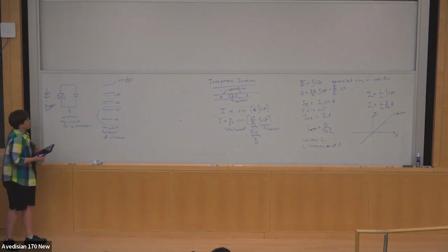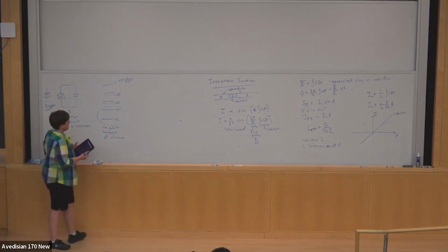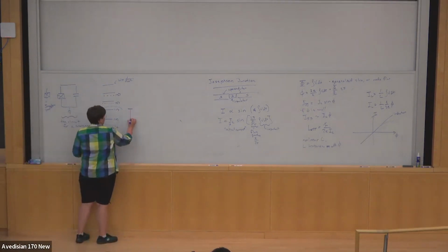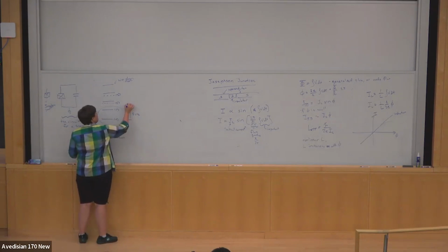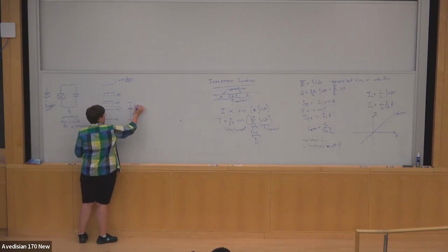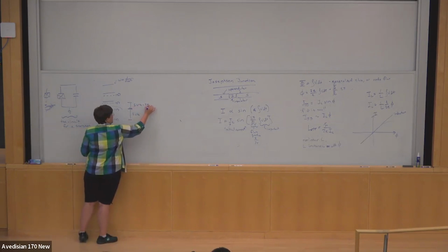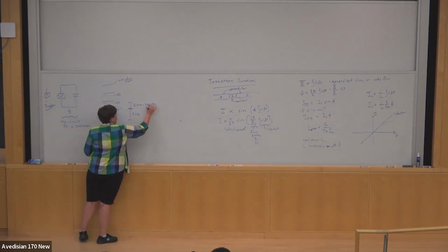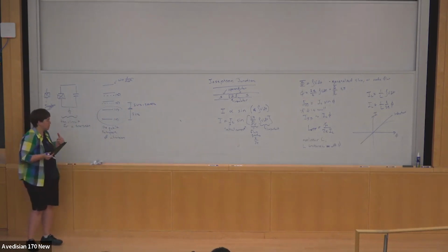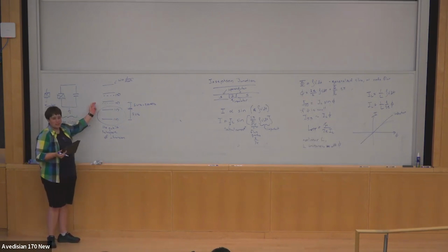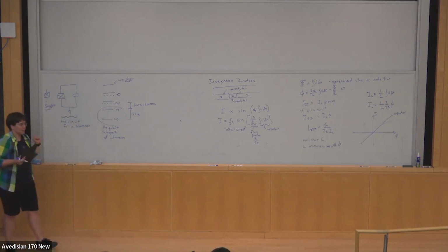And so one of the things that's really remarkable about the Josephson junction is that it's strong enough that this can be 5 gigahertz, and this can be 5 gigahertz minus 200 megahertz. And so you can get a huge frequency shift just from one additional excitation. And it's this anharmonicity that allows you to treat the lowest 2 levels of the transmon as a 2-level system.